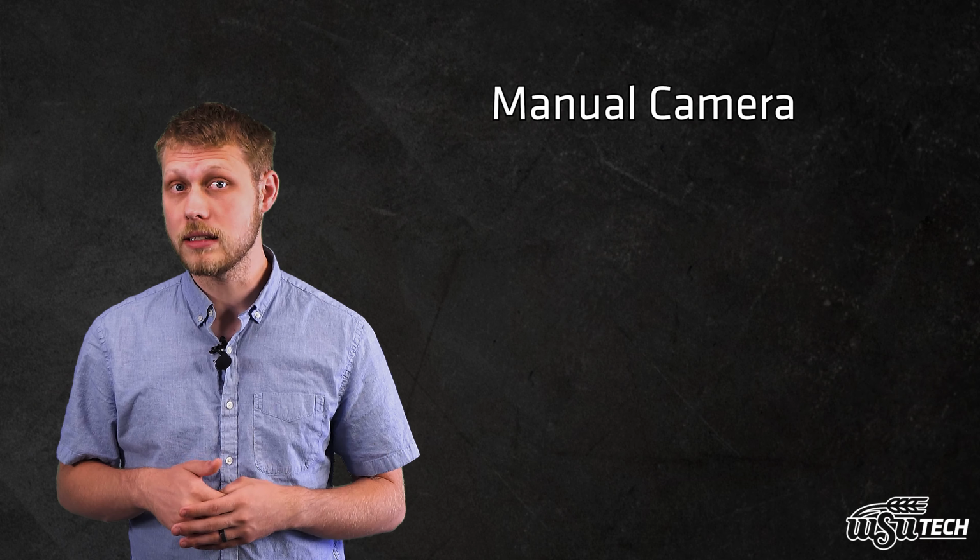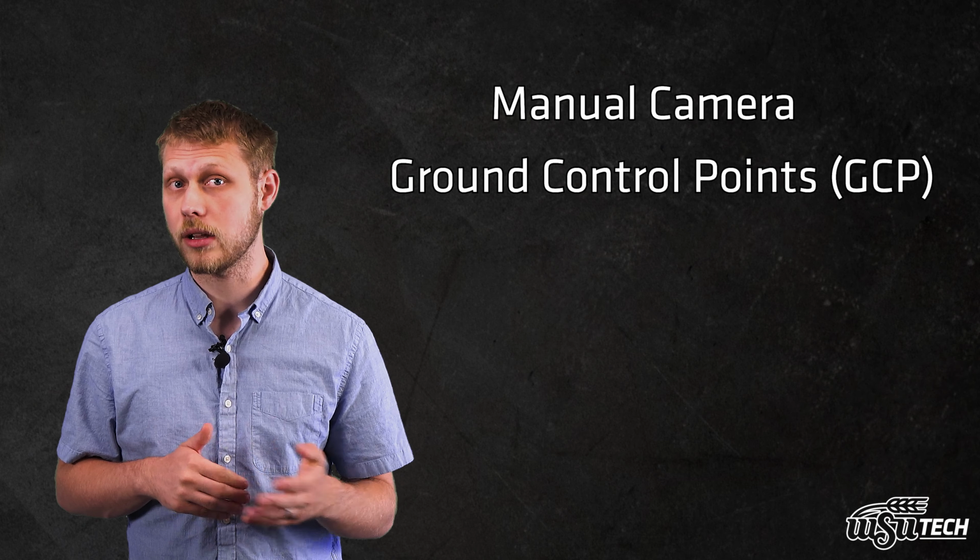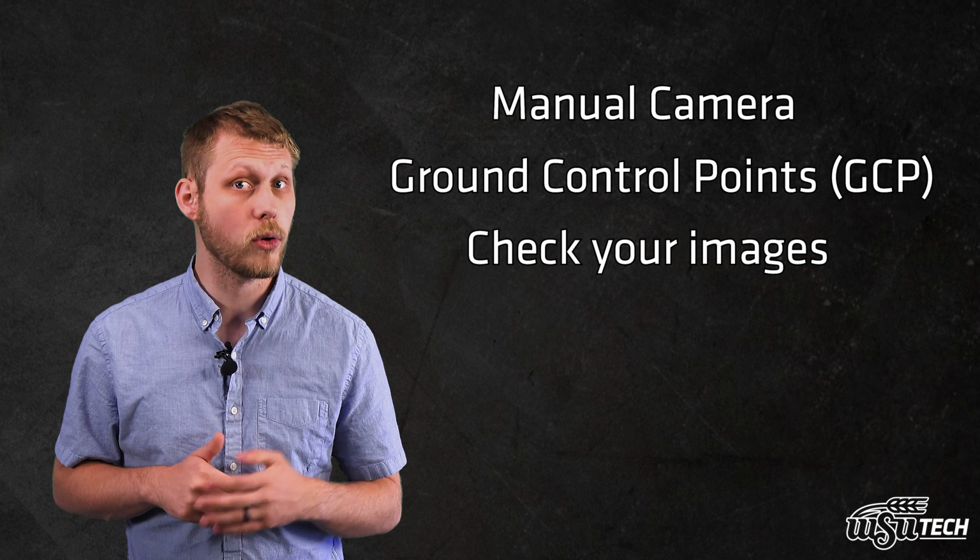Set manual camera settings, use GCPs for georeferenced accuracy, and always check your images before you leave the site. One missing or blurry image can throw off the entire model. Photogrammetry is a powerful tool, but only if you fly it with purpose.